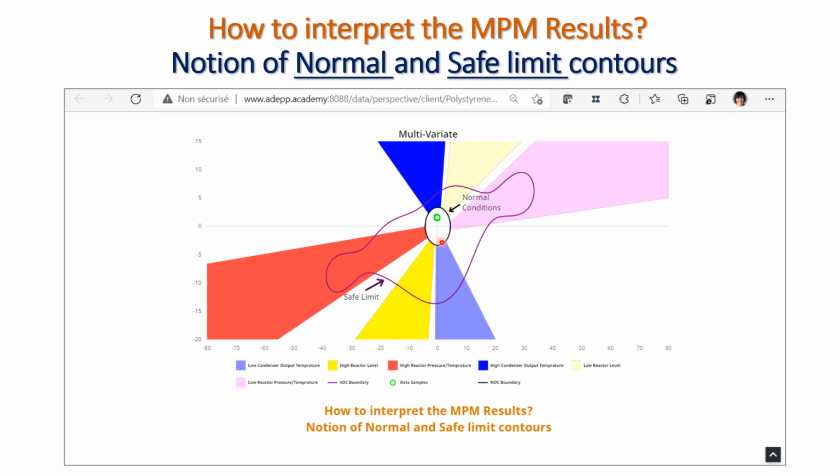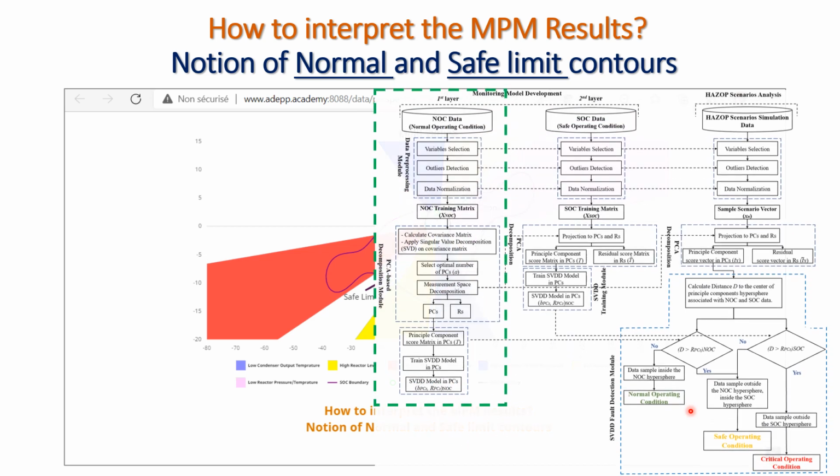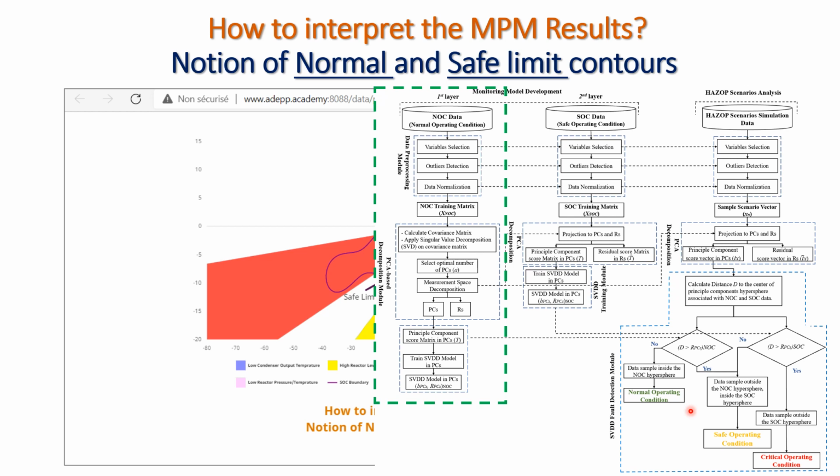To define the normal operating condition, or shortly NOC, for this study, we collected the input and output data from the real operating polystyrene plant in the industry for the normal operating conditions. When we are in the design stage, this data can be collected from the simulator. To initiate the monitoring method, simulation sample data under normal operating conditions are fed into the PCA to determine the most effective principal components, which lead to dimension reduction and better analyzing components. In this case, the dimension of process data is reduced to 2 through PCA from the original 4 dimensions.